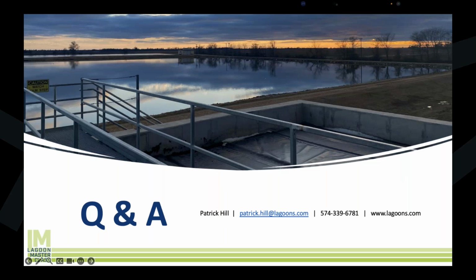Here's the first one. Does Kennett have a large school? I've seen instances where ammonia loadings increased during the school year and we traced it to a grade school. Our theory, the school had a large population of kids that weren't normally in the town on their sanitary sewers, and for whatever reason, when kids are at school, they tend to only use the restroom in a way that sends ammonia down the line.